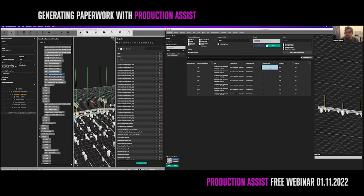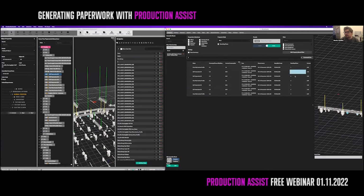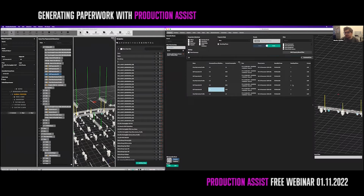So you see the first fixture, which is on C1, ends up at phase 1. The second fixture, or the next 2 fixtures, end up at phase 2. And you see that C5 is also ending up at phase 2. So it gives you a powerful way of looking at this. The nice thing about this is the resulting phase also takes into account hot patches. So if you have a hot patch in the system where you move stuff around, then it just automatically calculates the resulting phase based on the specific patch you've done with the specific hot patch in here.